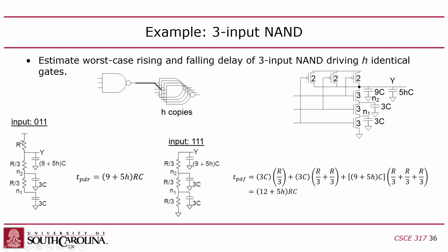So I've got one pull-up resistor here. Meanwhile, I've got 2 pull-down resistors, but all 3 of them have to be on to pull down. I still have 2 of them on, because 0, 1, 1 means 2 of my NMOS transistors are on. So I don't fully get to pull down; the circuit gets interrupted before I get to pull the output down. But you still have to consider the effect that has potentially on capacitance, because 2 of the 3 pull-down transistors are on.